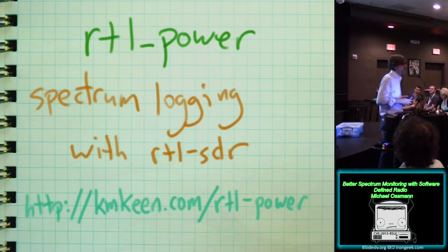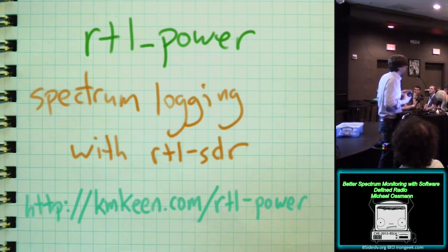And the main reason for that is that we have to control these things over USB, and there's some USB communication latency every single time we tell the radio to tune. So this technique is not good at all for capturing transient events. But it's super awesome for sweeping over a very wide range of frequencies and for doing it indefinitely, for as long as we want to.